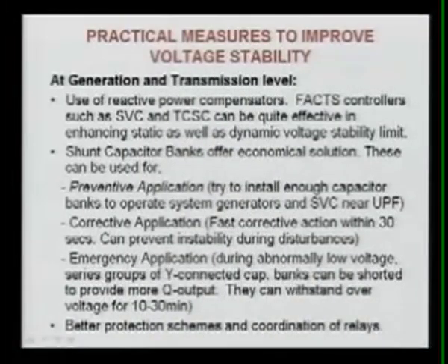The reactive power compensator is a must, and FACTS controllers such as SVC, STATCOM, and sometimes the TCSC, although it is a series device, can be quite effective in enhancing static as well as dynamic voltage stability limits of the system. In the transmission lines you can use FACTS controllers, and at the generation level you can generate more reactive power if your system is reactive deficit.